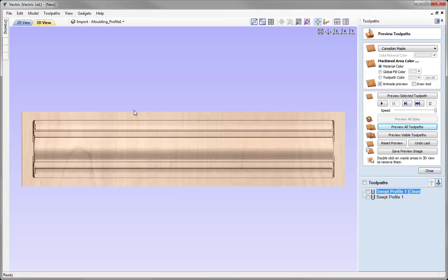So it's useful to know that we can take away the vertical pieces of the profile, as we don't really need those to calculate this kind of toolpath. And so if I wanted to cut this part out, what we could do is simply extend the drive rail, and we could create a boundary vector that would essentially profile around to cut the moulding out. So let's have a look at that.